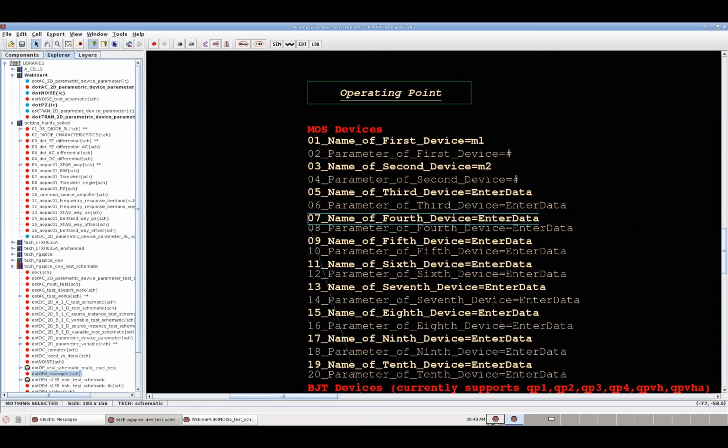Does it have to be 0.5, 0.6, or can we make it 0.45 or whatever? And then while playing around with Magic in your preview.efabless.com, I saw that one square is 0.05 microns. Can we count on this to say that the thinnest transistor is 0.4, and then the next one is 0.45 microns, or something else?